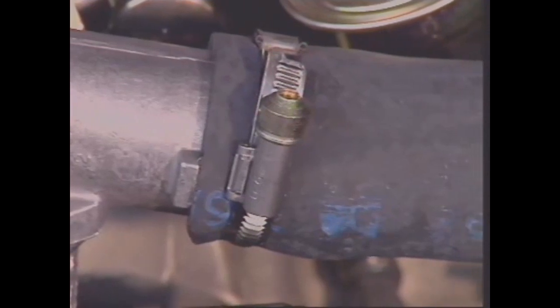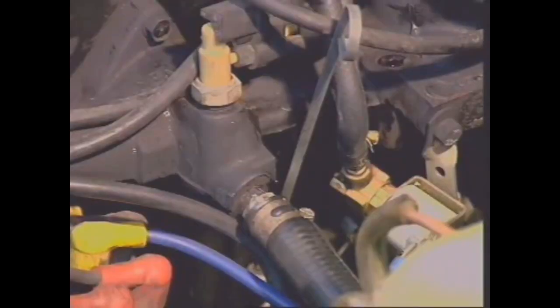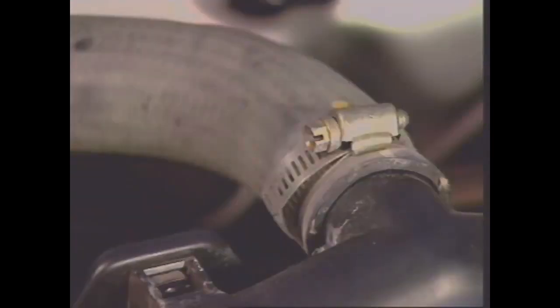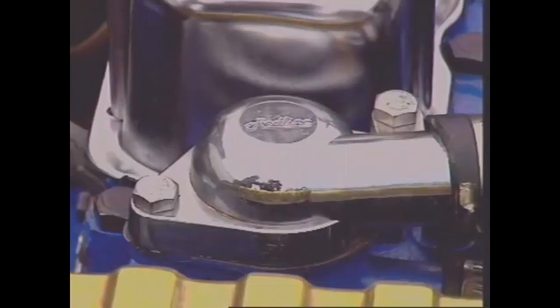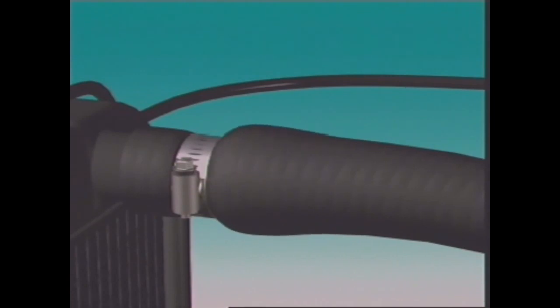Coolant hoses vary in diameter depending on the volume of coolant that passes through them. Heater hoses carry a smaller volume. Most hoses are made of rubber, and since they are subject to pressure, they are reinforced with a layer of fabric. They are moulded to a special shape to suit the model and make of vehicle. Some heater coolant hoses also have special shapes. All hoses are subject to hot coolant and high underbonnet temperatures, and they can deteriorate and fail.